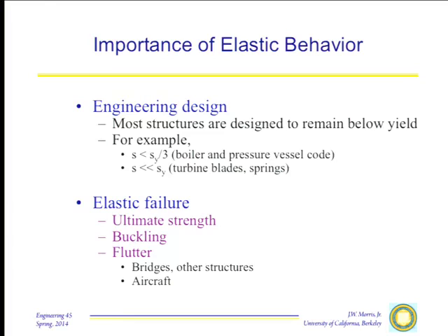Buckling. The ordinary way that buildings fail in earthquakes, for example, or that cars dent. When you dent an automobile, yeah, you deform it plastically, but it is not exceeding the yield strength that does that. If you take a column, the classic example, and you push down on it, the column will bow out.